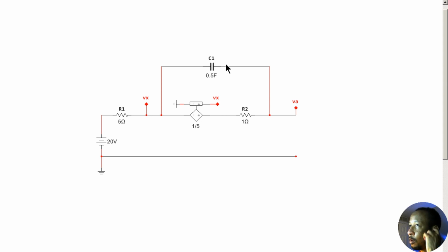If you have a capacitor, then you're going to get into either derivatives or integrals, and this is to hopefully ease that and make it easier to solve by using an algebraic expression in the S domain, as opposed to keeping it in the time domain and solving it with differential or integral type expressions. So that is it. The circuit checks out well, and that is the type of response that you have at the terminals of VA with respect to ground. So that is it.